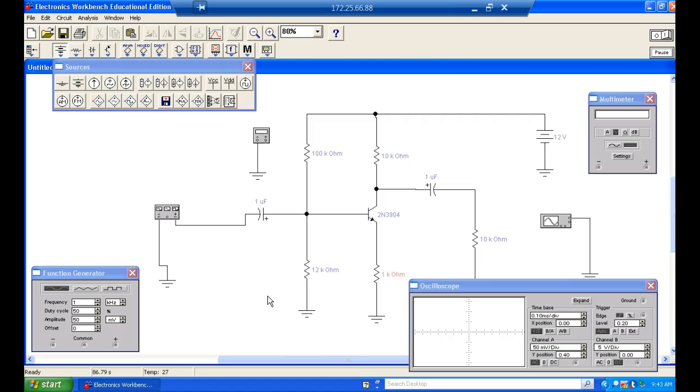Beta's gone again, but also we're dealing with infinity on that side. So our base voltage should go up just a little bit, because this guy over here is not in the circuit at all anymore, right? Base voltage will go up a little bit. Transistor should do what? Cut off. Yeah. If you don't have emitter current, you don't have collector current, right? You understand that? So no emitter current, no collector current. So transistor should cut off.